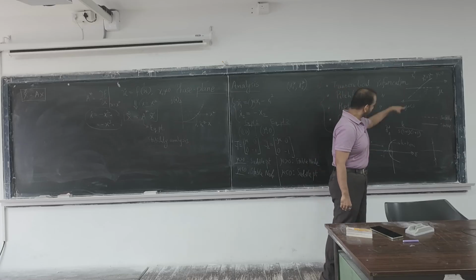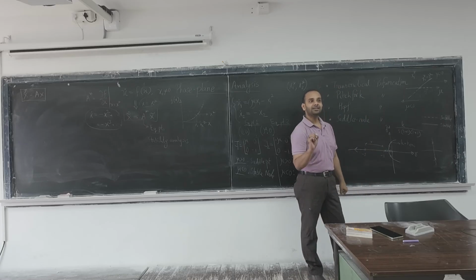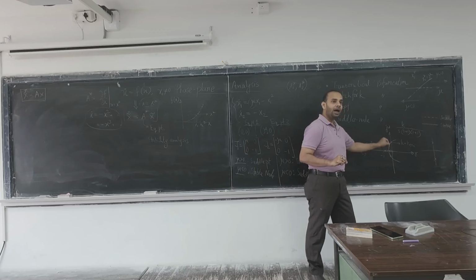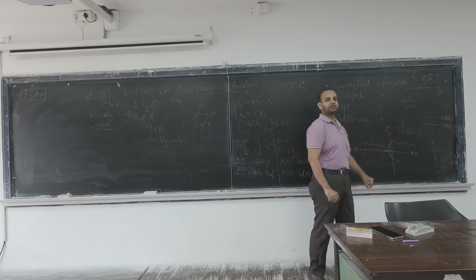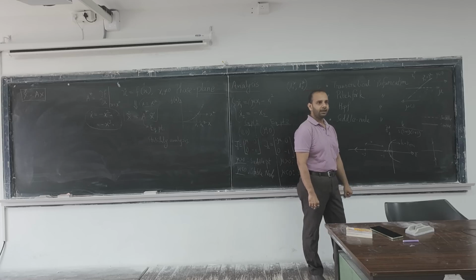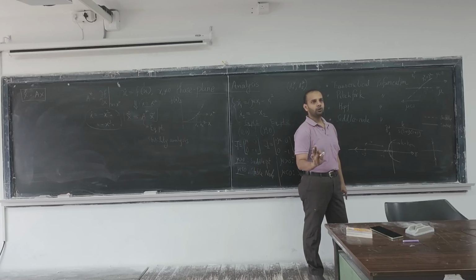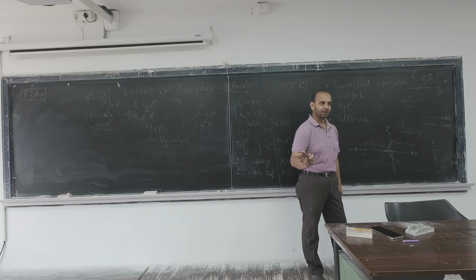So this is also something like that. It is just an analogy. Otherwise, no relation. It is bifurcation and it is a root locus diagram. But just to give you the concept of boundary point, I wanted to recall this. K is the critical point in which sense? If K is less than K critical, then it is closed loop stable. But if K is greater than K critical, then unstable.